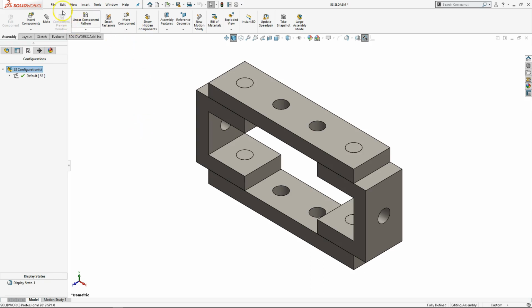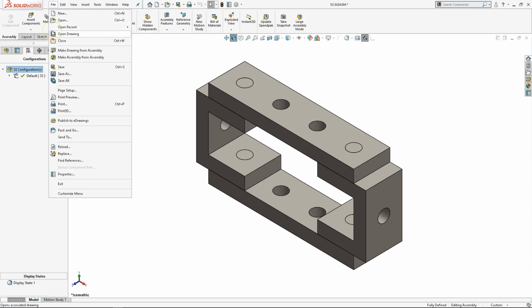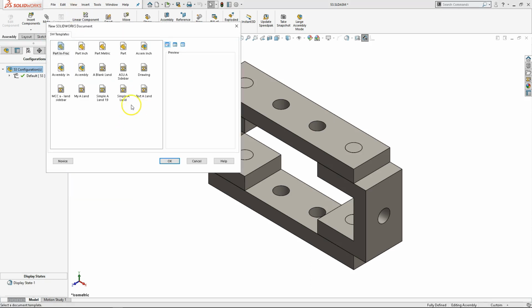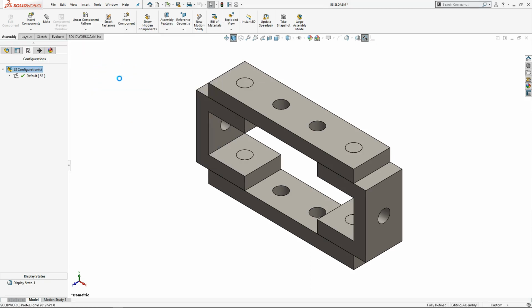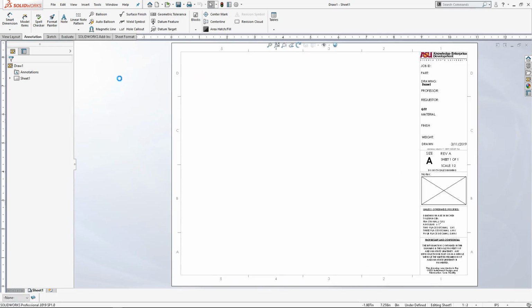So what I was shooting for was there is a whole other level of going into drawing templates and creating these drawing sheets. So if I grab, well, I'll look at the sidebar one. So this is something to go through, and it has those relations. Each of the parts travels with its metadata, and then when it makes it into the assembly, it automatically populates my drawing template.